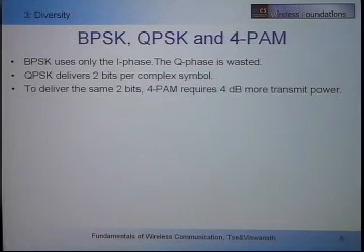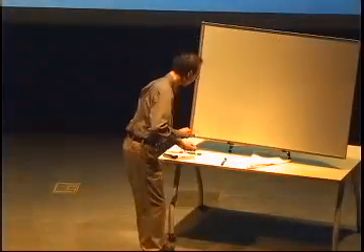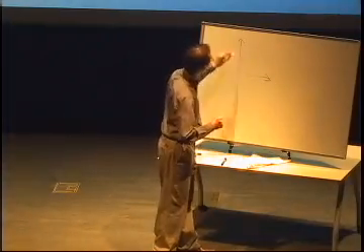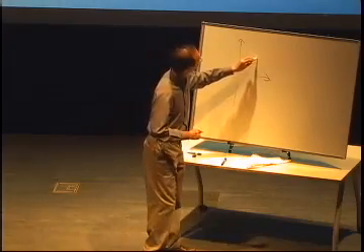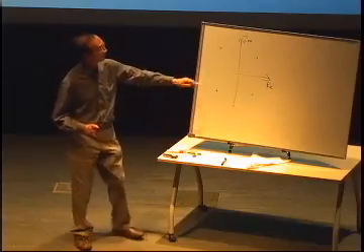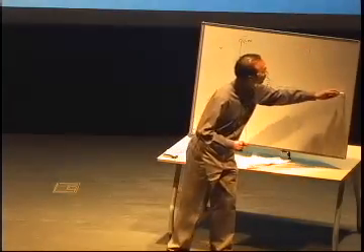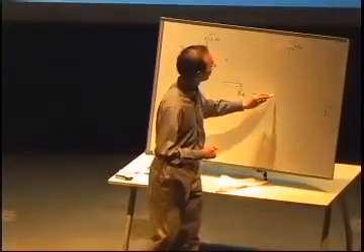And here is another notation, PAM. PAM stands for Pulse Amplitude Modulation. The names become senseless because they were invented 50 years ago for some other odd historic reasons. PAM really means, it's a complicated way of saying, I want to send 4 values to send 2 bits. Okay? So in other words, the comparison here is that, okay? QPSK, the constellation of QPSK is like this. So this is my real and this is imaginary. Okay? This is QPSK. These are my 4 possible values. Okay? 2 bits. For PAM, the same 2 bits, but I only use the real part to send, means this.